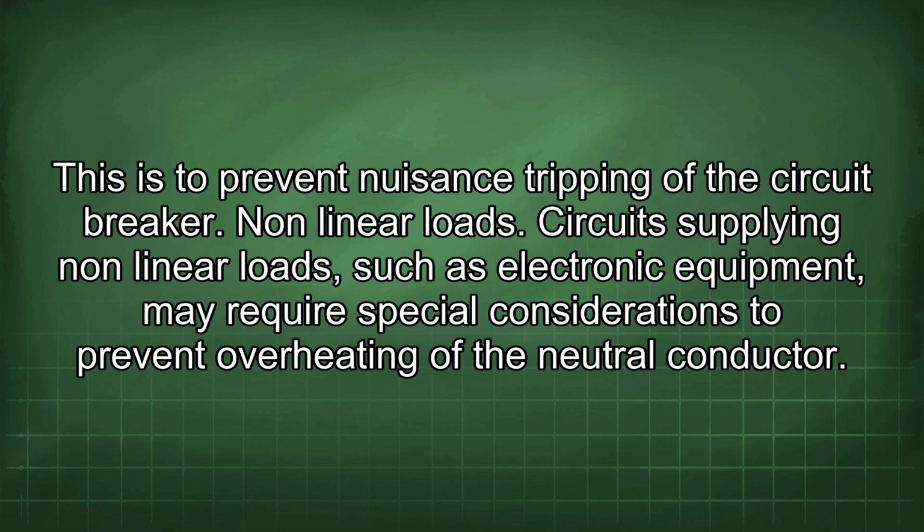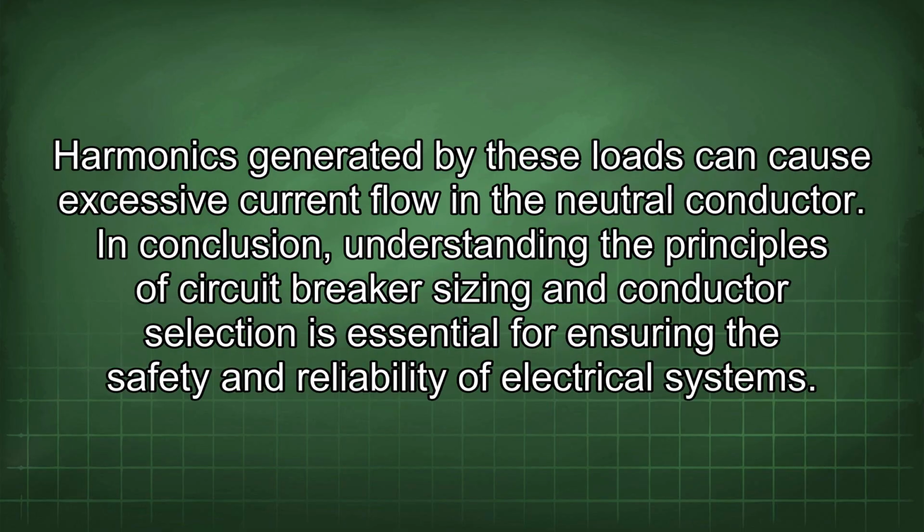Non-linear loads. Circuits supplying non-linear loads, such as electronic equipment, may require special considerations to prevent overheating of the neutral conductor. Harmonics generated by these loads can cause excessive current flow in the neutral conductor.